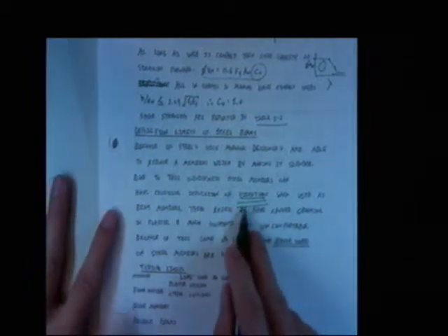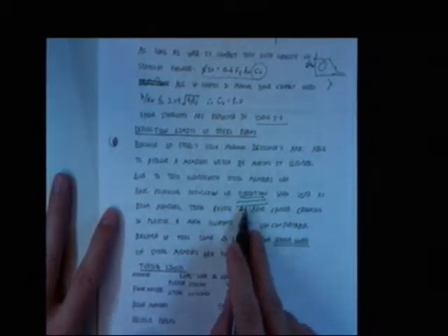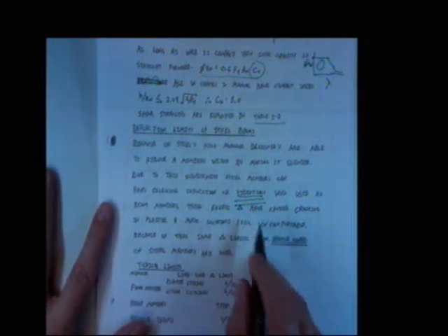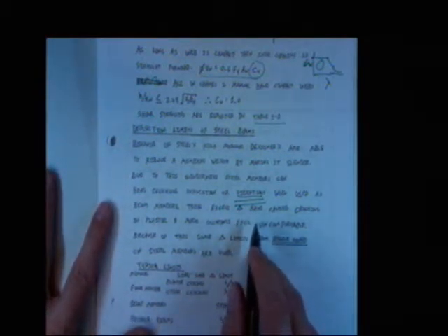And you want your structure to not be at that same natural frequency. Because if it is, then as it's loaded at that natural frequency, it will become excited. Okay? And typical deflections that aren't that big of a deal get magnified. And that's what dynamic loading is. That's what dynamics is about. Okay? Understanding that.